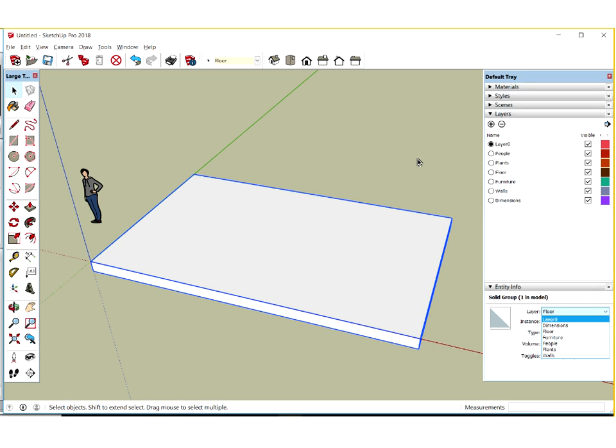Perfect. Now, just to reiterate that process as well, we can click on our lovely assistant Stacey here on our screen. If you've got a human figure somewhere in your model, you'll also see I've already got Entity Info open. It'll stay open until you close it again. You can see the name there and some basic info about it. You can place her on a layer called People. So if you need to quickly create another layer, you can click on the plus sign and do that, and then you can put her on that People layer.